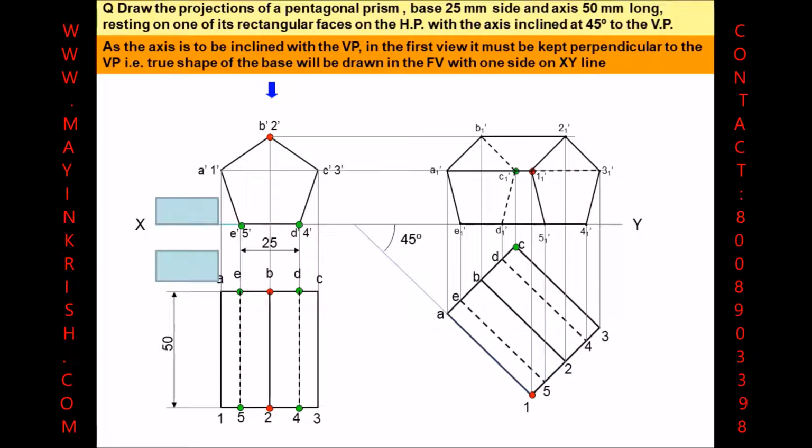Now if we observe the final front view, we have a few dotted lines here. What it means is that when we view in this manner, in the front view of this particular object, other than C3, whatever edges we have will be observed. The observer is viewing in this manner, and the C3 longer edge is far away from the observer, so he can't observe C3 clearly.